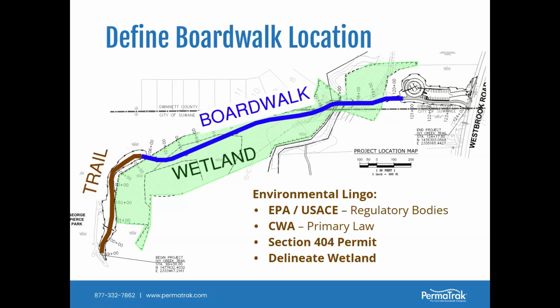However, the EPA and the Corps of Engineers, they're the regulatory bodies. They have some rules that you must follow if you're in a delineated wetland area. And it all goes back to 1972, when, if you're aware of or have heard of the Clean Water Act, the Clean Water Act in Section 404 provides some permitting guidelines and regulations and what you can or can't do inside a wetland. Particularly, it says that they discourage putting fill into the wetlands. Therefore, the need for a boardwalk. The trail has to become elevated. The boardwalk is nothing more than an elevated trail in a wetland.